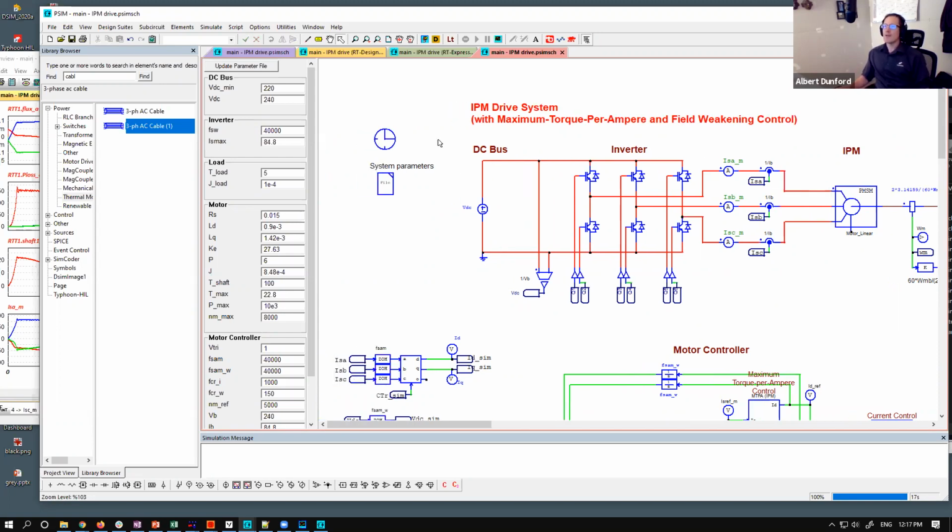Then, as you keep going further, changing the front end from an ideal DC source to maybe a LISN network, or front end filtering, or even a DC bus transmission line model, to mimic how your actual machine, inverter and power electronics are sitting in their actual prototype or developed product state. So all that can be looked at.